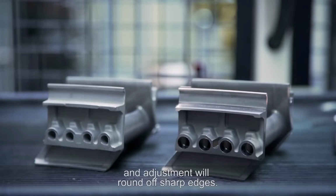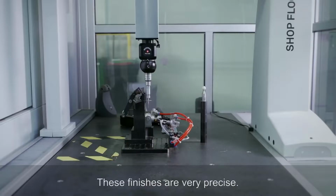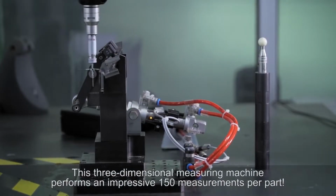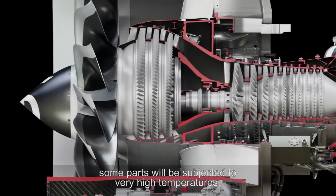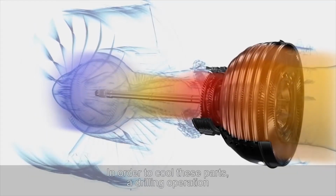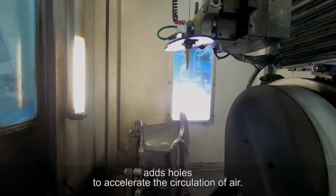An adjustment will round off sharp edges. These finishes are very precise. This three-dimensional measuring machine performs an impressive 150 measurements per part. According to their position and their function in the engine, some parts will be subjected to very high temperatures. In order to cool these parts, a drilling operation adds holes to accelerate the circulation of air.